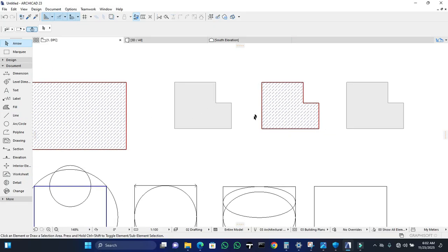On the other hand, I can simply take these parameters and inject it onto this one. That was one of the first things we talked about in our first video, Introduction to ArchiCAD. You can find those commands here. Pick up parameters, inject parameters. So if I click on pick up parameters, I can take this parameter, move to what I want to transform to it, and inject the parameter on it. So if I click on it or I press Alt C, same thing.